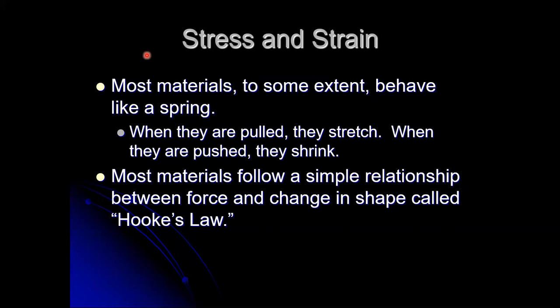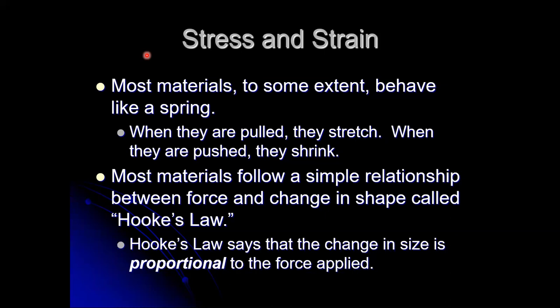This nice simple proportionality fails when we put too much load on things. There is a limit to how much force we can put on something to have it obey Hooke's law, and that's a limit we're going to have to become familiar with as we get into practice on this. But Hooke's law is a law of proportionality. It says the harder you push something, the more length change you get. If you're more familiar with electricity, you could think of Ohm's law as a rough equivalent of Hooke's law. Voltage is pressure, current is essentially change in motion, change in shape.